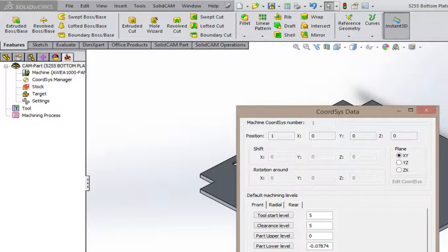I'm not cutting in the material. If I'm below the surface, the number says a negative, I know I'm bad, I'm in the material, I'm potentially in trouble, I'm cutting material. So that's the way I like to define it. You could define it a different way, but you need to be careful. If you define your 0 down here, and then you don't make your upper level high enough, you might be dragging through material every time it moves. So I like to define it this way.